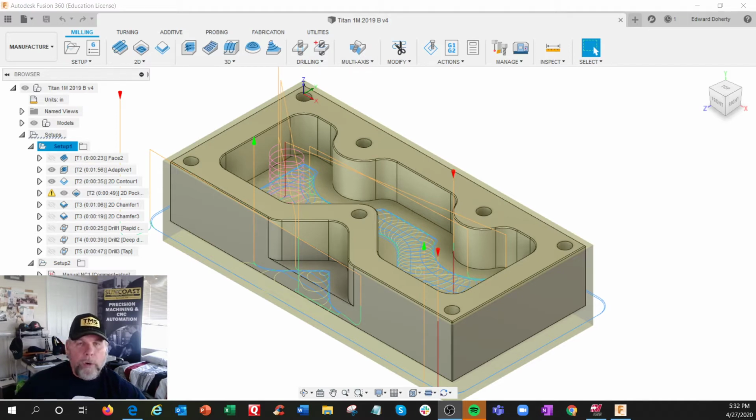One thing we used to do in the old days was strip out all the N numbers in the code. You could do that in your code editor. You don't really need the N numbers. And when we got really crazy, we used to take out all the spaces between the G code to compress the file. It doesn't become as readable, but who really wants to read the file anyway? So anyway, settings in your CAM system.